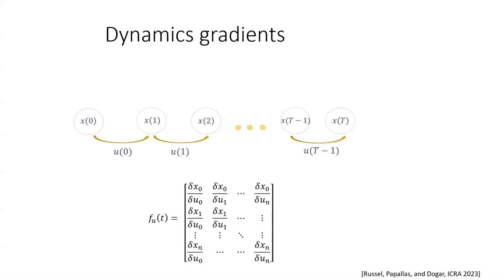So you can just take the derivative of your expressions and then compute these. But when we have these contact-based formulations about multiple objects, that is usually not possible. So what happens in trajectory-based optimization for robotics is these are computed using a method called finite differencing, a method to numerically compute the derivatives.